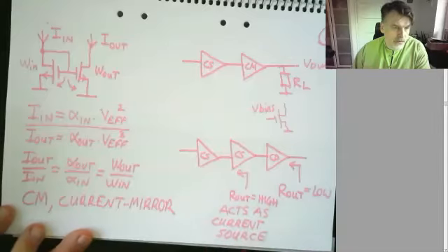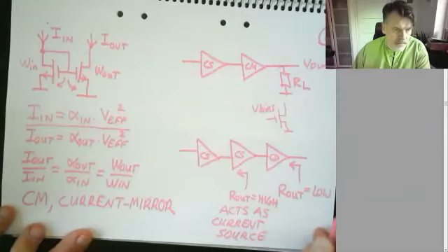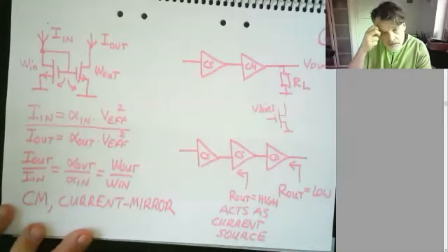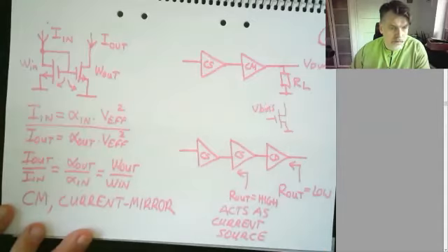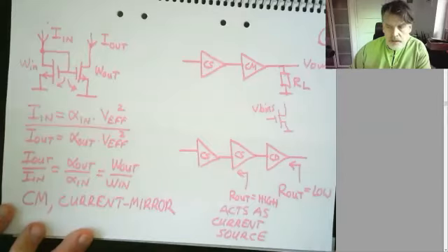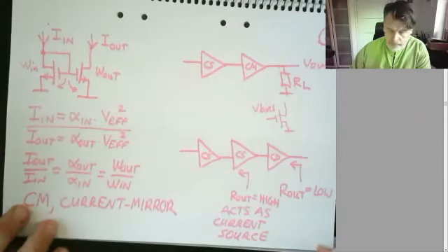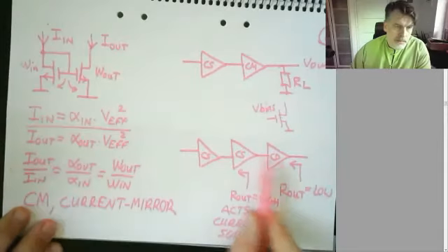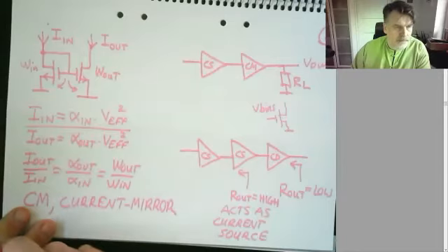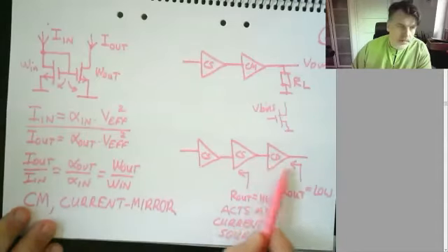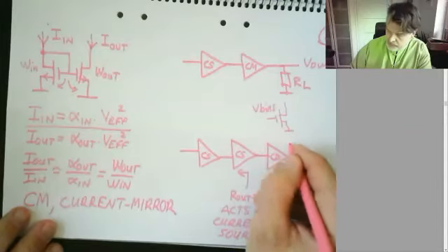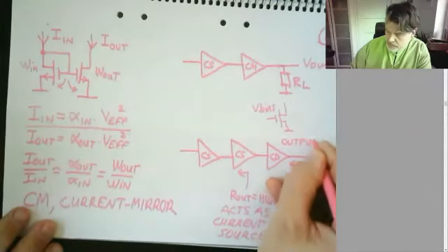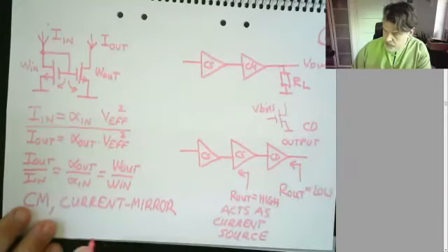So if you go back to the fundamentals of electrical circuits, in the Norton equivalent, for example, and the Thevenin equivalent, the ideal current source has an output impedance which is infinite. And the ideal voltage source has an output impedance which is 0. So those are different ways to combine them in order to mimic certain behavior of the amplifier, dependent on your load. So common drain typically sits at the output, more or less always.